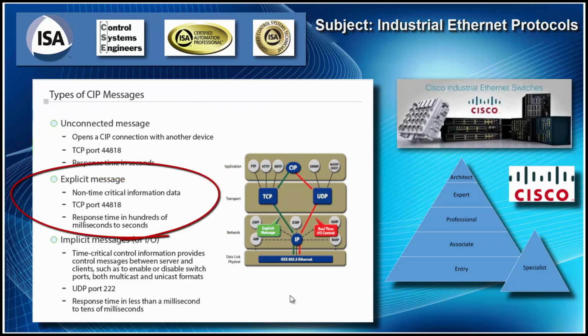Explicit messaging connections provide generic multi-purpose communication paths between two devices. Explicit messages provide typical request and response oriented network communication and are always made to the message router object. Each request contains explicit information that the receiving node decodes, acts upon, and then generates an appropriate response.